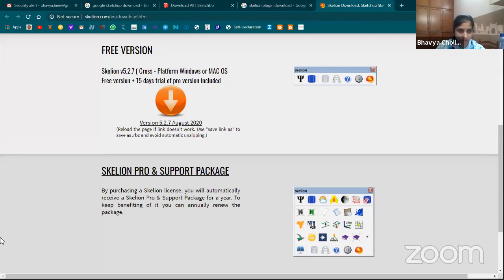Ma'am, we have considered the height of placing the module and the spacing between string to string construction. Generally, for the structure here, for the time being, I've considered a normal height because my tilt angle is 20 degrees only. But if you go with other tilt angles, like higher tilt angles or stack considerations, where you have higher shadow considerations and you have to increase your structure height too much, then you have to mention the height of the module also, or you have to create a component called structure, insert that, and put your modules above it.